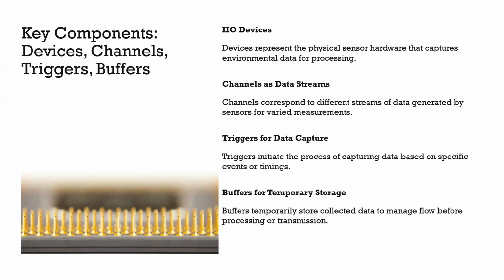Next is the buffer. The buffer management is well taken care of by the IO subsystem. For example, if you are receiving data from a sensor which is pumping the data very fast, and you write your own data handler, there is a chance that you can miss the data. But in the IO subsystem, they have a ring buffer. We'll be seeing that in the next slide.